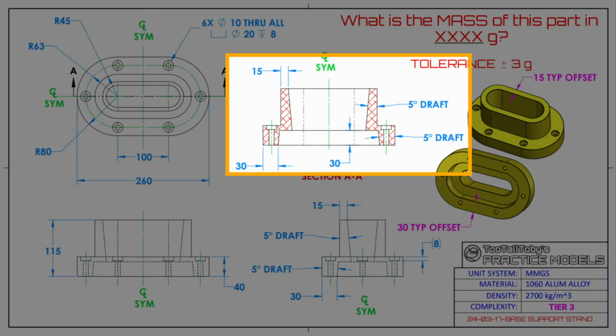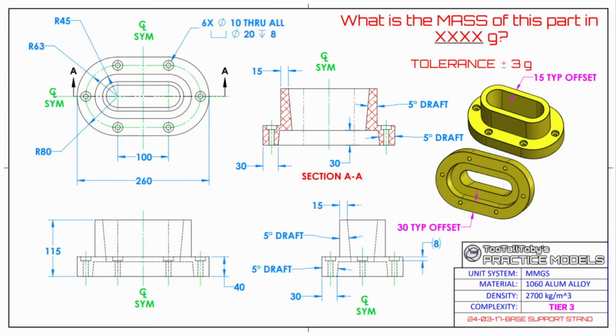And again, these dimensions are also oval in shape, but they have a 5-degree draft. But essentially, like before, we will define these ovals using the offset tool. But then as we extrude, we'll just use Plasticity's angle parameter to define that draft, to do that extrude cut. And then after all of that, we'll just need to finish off by creating these inset through holes.